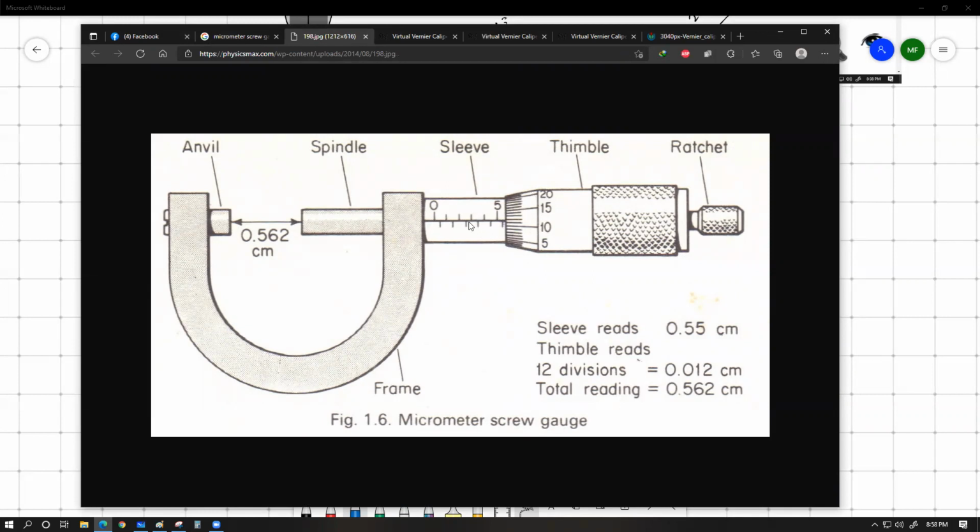If you have a look over here, this main scale is actually divided in millimeters, because here we have 0, and you can see on the top side 1, 2, 3, 4, 5. After 5 divisions, we have 5, and each of these smallest divisions represents 1 millimeter. Interestingly, we also have lower division marks at the midpoint of these millimeters. So practically speaking, this scale has half-millimeter divisions as the smallest measuring mark. This is 0, 0.5, 1, 1.5, 2, 2.5.